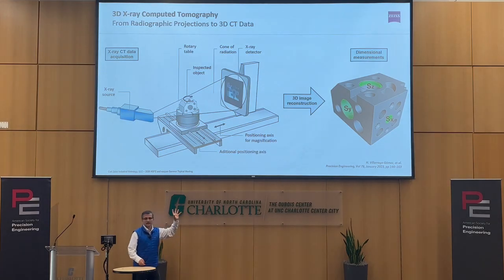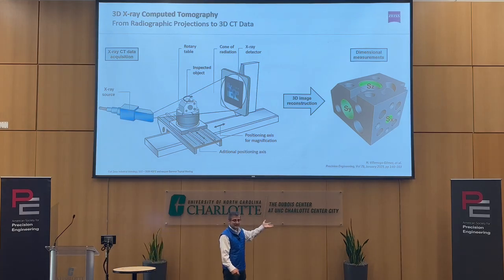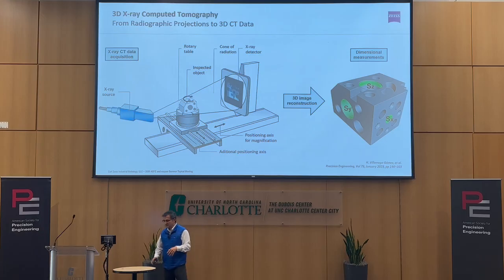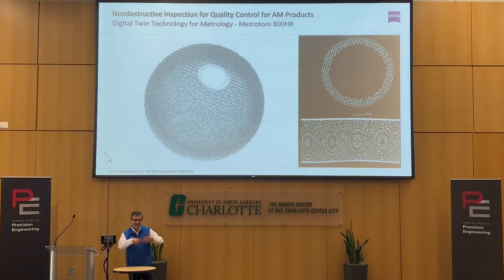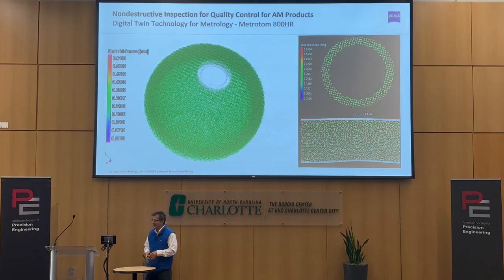But the basic idea is that they knew how to do some sort of calibrations, and that's the main differentiation as an X-ray, as opposed to a classical X-ray imaging, because you need to convert the imaging or the voxels into a dimension, and that dimension is to be corrected somehow for deviations, and then now you're more confident you can do dimensional metrology. Once you are confident that your system can do that, then you can do all kinds of comparisons against a CAD model.